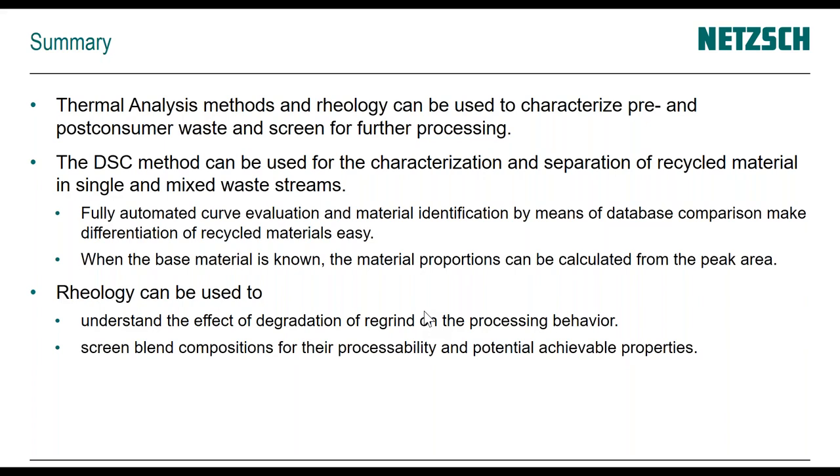But as you've seen in the example of what we call the polystyrene recyclate, we had that PP with HDPE, even in a small proportion, the DSC was sensitive enough to pick up the HDPE. And when the base material is known, I think that is very valuable, and I've used that a lot in my own practice.